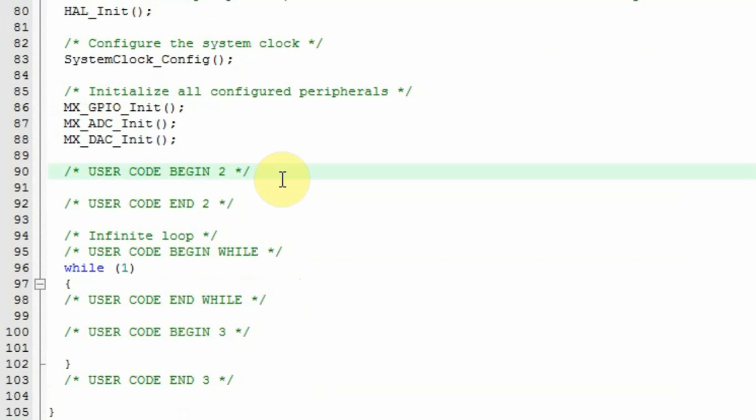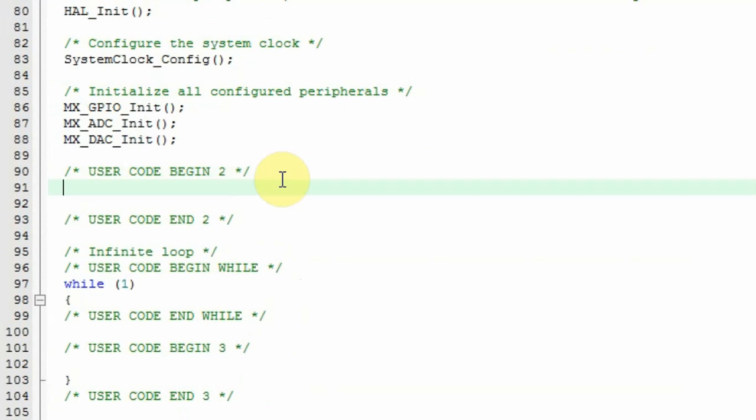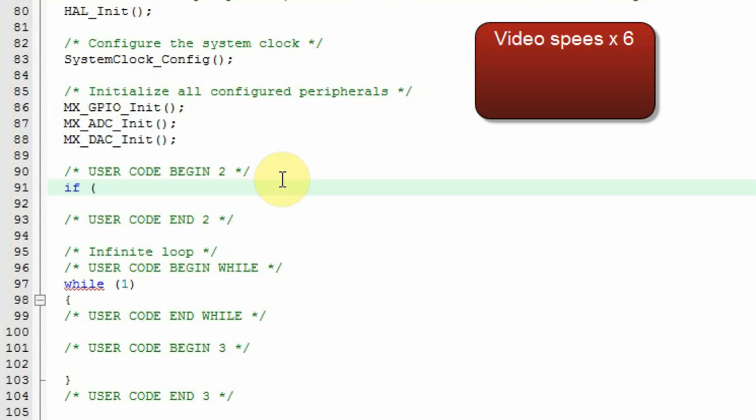Now the STM32 has an accurate ADC, and in order to get all the benefits, there are 2 things that need to be done. One is a calibration, and the other one is the voltage difference depending on the VDD that you're using. This I'll show in a different video, but the calibration is very easy to use, and I'll show it here.